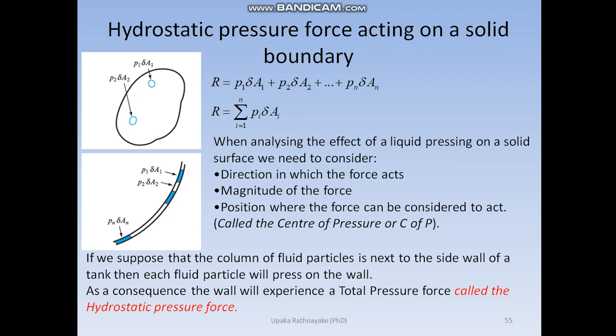We need something else as well. When we look at the equilibrium, we need to know the location where this resultant force acts. When it comes to the hydrostatic pressure force, we call this particular location the center of pressure. When we limit our studies to fluids, we call this force the hydrostatic pressure force.